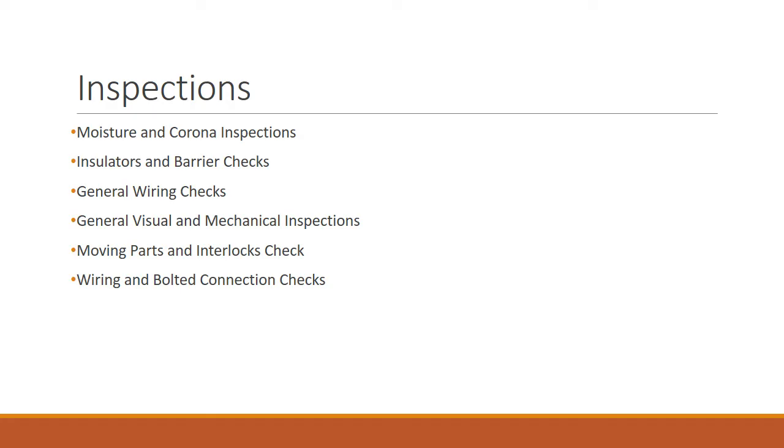Now, the third type of inspections that should be done are the general wiring checks. If the wires are part of a key protective circuit, such as a circuit breaker's protective relay, loose control wires might cause catastrophic failures. If faulty connections warm and lose integrity, other vital operations such as electrical charging and circuit breaker reclosing may be hampered. To avoid damage during ordinary operation of moving parts, make sure all wire connections are tight and secure, especially when removing draw-out circuit breakers or opening and shutting cubicle doors.